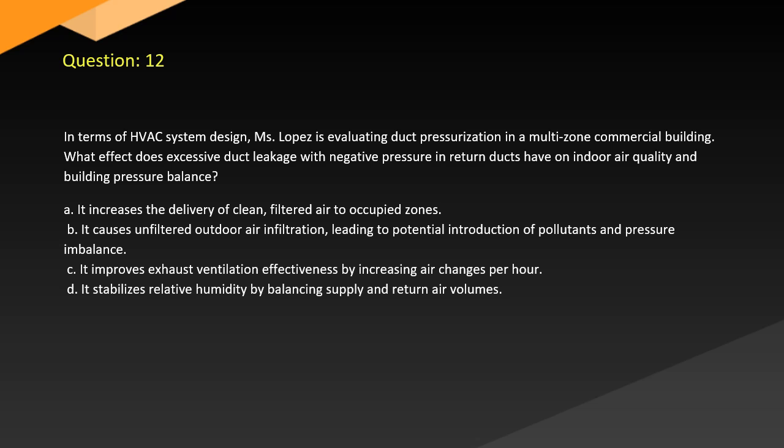Question 12. In terms of HVAC system design, Lopez is evaluating duct pressurization in a multi-zone commercial building. What effect does excessive duct leakage with negative pressure in return ducts have on indoor air quality and building pressure balance? A. It increases the delivery of clean filtered air to occupied zones. B. It causes unfiltered outdoor air infiltration, leading to potential introduction of pollutants and pressure imbalance. C. It improves exhaust ventilation effectiveness by increasing air changes per hour. D. It stabilizes relative humidity by balancing supply and return air volumes.